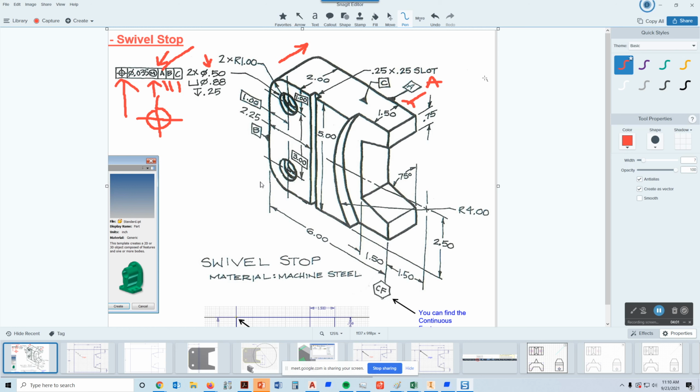And of course, we're not using a drill to make this thing. We're probably using a CNC mill or something like that. But the point is that however we cut that hole, whether we bore it or drill it, our primary concern is how perpendicular it is to datum plane A. And datum plane A is like a horizontal datum plane in the background there. And that's usually your primary datum on holes, the plane that would be for measuring perpendicularity.